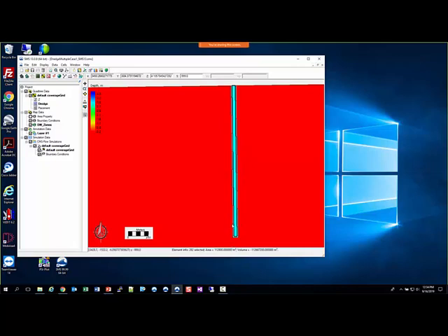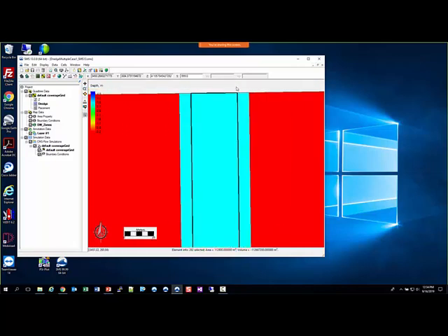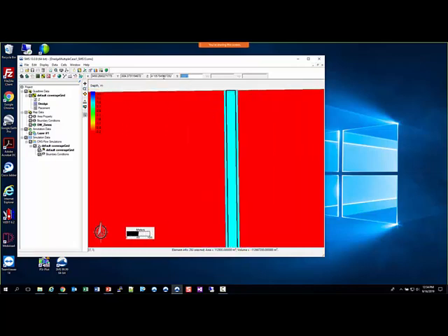So that's basically the cells that we want to modify here. So we're going to change this S value from -999 to 6. And make sure you get rid of that negative sign because sometimes they're a little sticky. If you select something, it sometimes misses that minus sign.